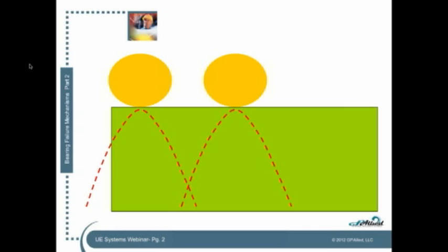So what happens is we get pressure. The balls or rollers are putting pressure down on the outer race. Of course, they're also putting pressure up on the inner race while they're in the load zone. So you can imagine here's two balls or rollers in the load zone, and these stress cones beneath them is how much stress or pressure or force they're putting on the outer race. And you can imagine in your mind the flip side above them, they're doing the same thing on the inner race. So what happens then is if we were to follow this spot right here where my mouse is, and we watch the balls and rollers go past that spot, every time a roller or a ball passes a given spot on the inner race or the outer race, there is a compression of the face of the race. And when that ball passes, that compression is relieved. And then the next ball or roller passes, and it compresses and relieves and compresses and relieves.